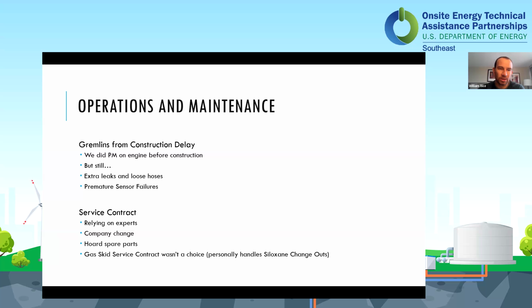But even with the PM work we were doing on the non-running engine, we still ended up having a lot of leaks and loose hoses and some other premature sensor failures just because the engine sat around for about a year before we were able to turn it on. So of course I wouldn't recommend doing that. Obviously coordinating install at the same time as when it shows up is much better, but it was just sort of the unfortunate circumstances that we were in.